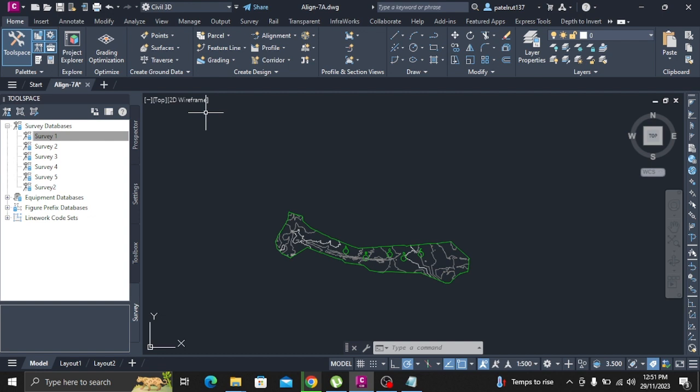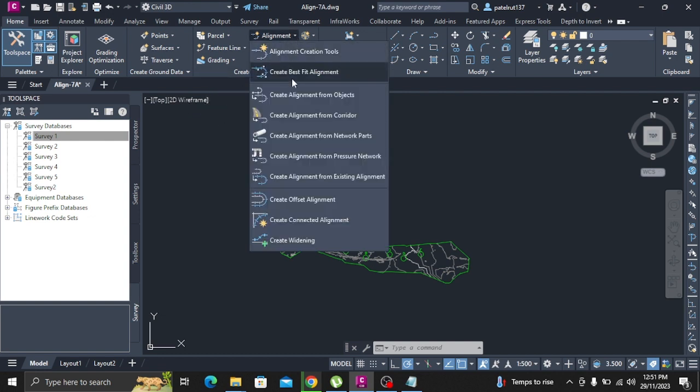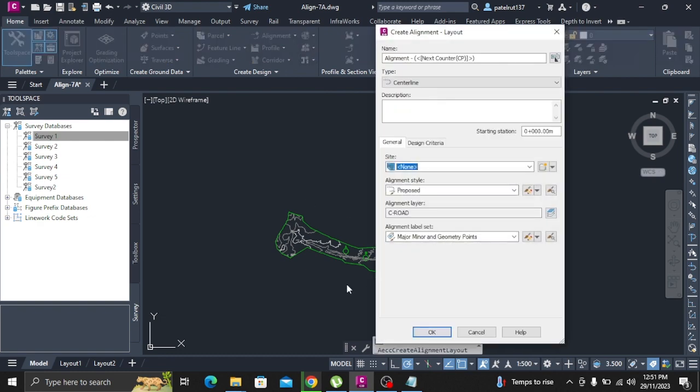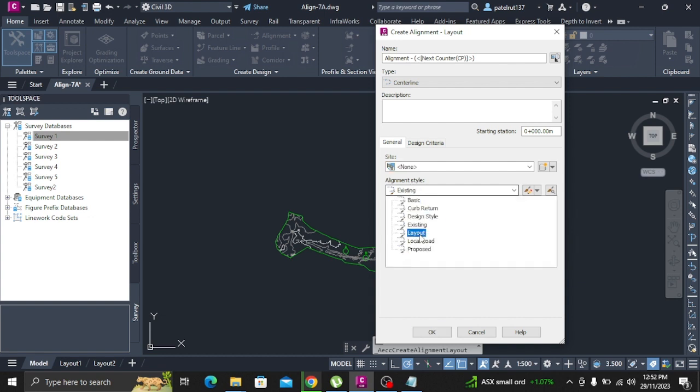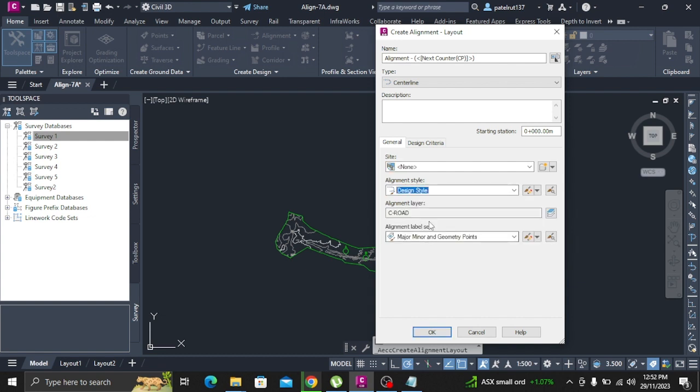On the Design Criteria tab, for starting design speed, enter 50 km per hour. Select the Use Criteria-Based Design checkbox in the Use Design Criteria File area, and click. In the Select Design Speed Table dialog box, select _Autodesk Civil 3D Metric Roadway Design Standards.xml. Click Open. In the Default Criteria table, in the Minimum Radius table row, change the value to AASHTO 2001 eMax 6%. In the Use Design Check Set list, select 50 km/h roadway length checks.